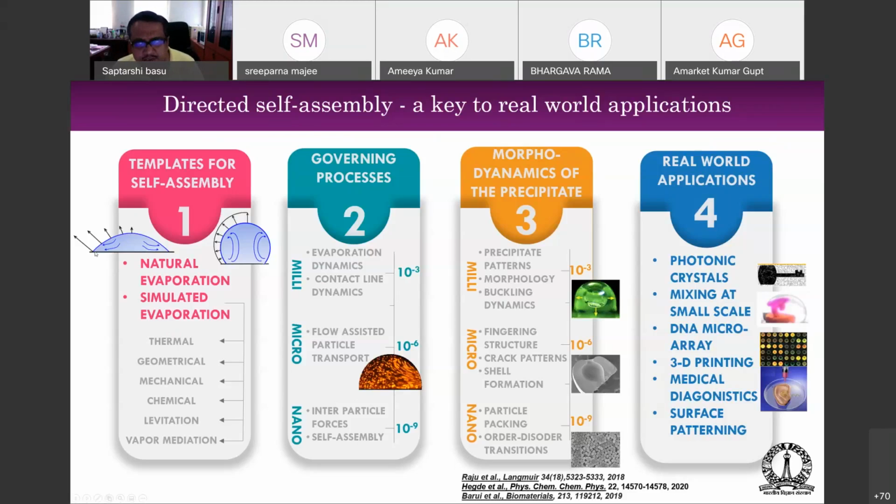So this is a droplet, for example, which is sitting on a platform, and this is another droplet sitting on the same platform. One is hydrophilic and one is hydrophobic. Now, depending on whether it is hydrophilic or hydrophobic, if these droplets contain particles, you will have different patterns of deposits that are left. Try this with a coffee drop on your table. If you dry that coffee drop, you will find that there is something called a ring-like precipitate left on the surface. That happens due to a particular flow phenomenon called capillary flow, which gives rise to that kind of surface pattern.